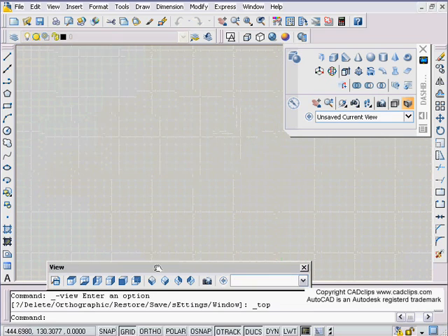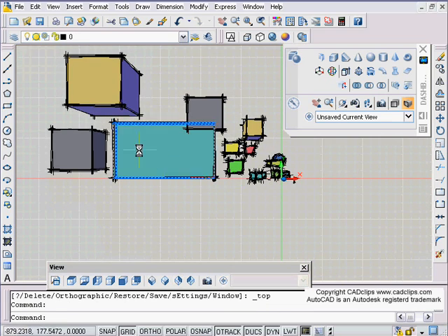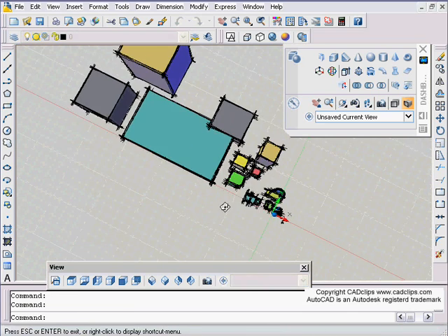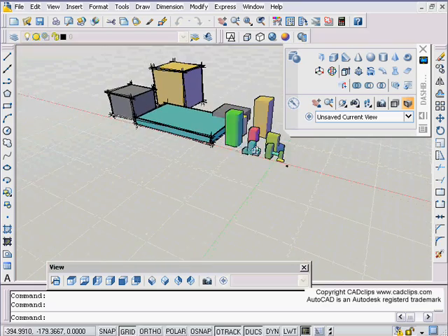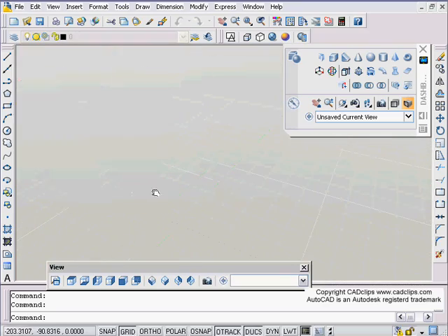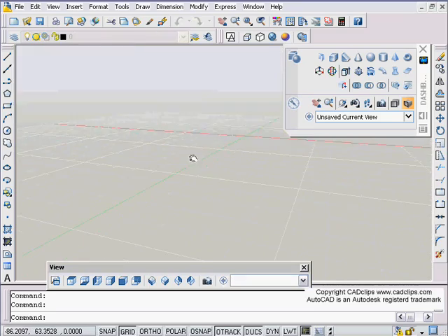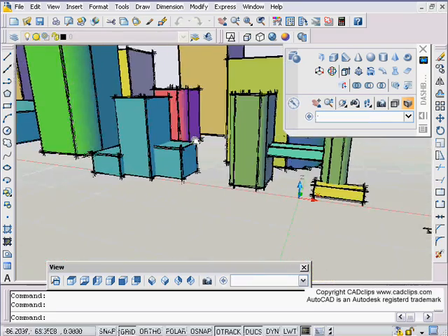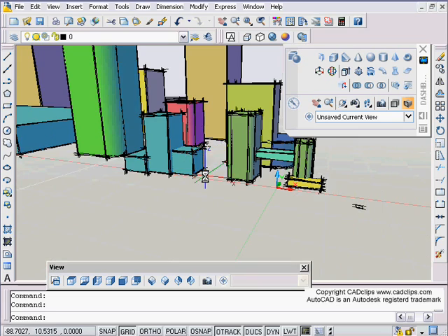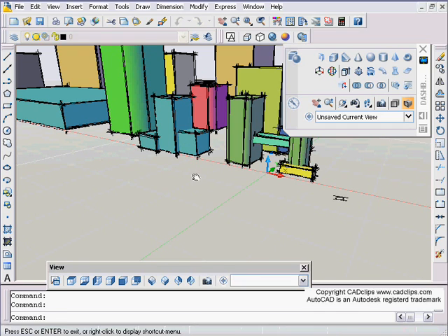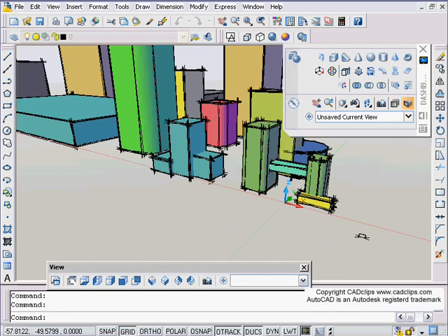And notice that even when you're in a top view over here, you can still be in perspective view. You can see it's kind of a neat view. And then shift middle mouse button, we can quickly zoom in over here. Okay, and I like kind of drawing in this mode, and we'll learn how we can set up some cameras. And all I'm doing is middle mouse buttoning and panning around with that grid and everything. And I used my ACAD 3D DWT template to start this off.